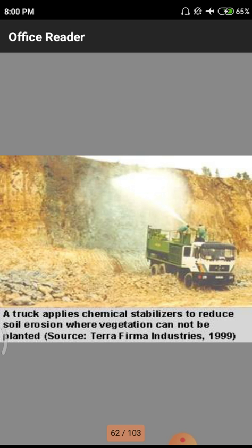Why? Because in this particular case there will be slidings whenever forces act on the structure. That is a totally hilly structure with rock and mud strata. Mud particles lose strength whenever there is a force application on the structure, so some sliding of small rocks may take place. To arrest those sliding forces generated in hilly areas, we have to go for this kind of stabilization. We spray the chemical content associated with the water with a huge amount of force. Due to that force, there will be some formation of bonds and stabilization takes place. Due to that stabilization process, there will be no sliding in future. It is one case study they have taken.